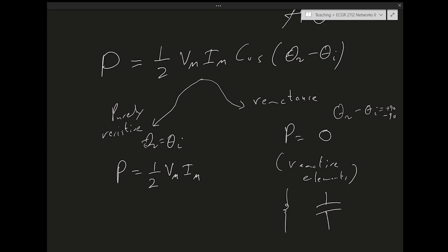It's like a spring. The spring is constantly absorbing and supplying energy or force. So the same thing, a reactive element is constantly absorbing and supplying power, but on average, the power going through it is 0. That's a very basic property of reactive elements. Only resistive elements or the resistive part of the circuit absorb average power, sorry.